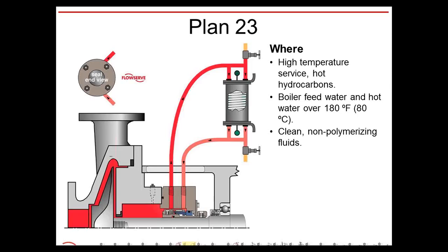Again, these have to be very clean fluids, because you are using a heat exchanger, and you can get fouling. So non-polymerizing fluids are really important here. And you also have to be careful with the types of fluids, making sure that they don't coke up and foul your heat exchanger.